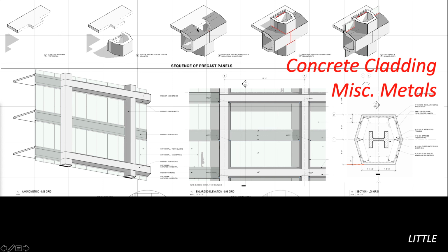Even if you've got a diagrid, you will have some kind of either a self-insulating cover or insulation and a metal cover to basically isolate that from any kind of fire resistance. And I thought this one was interesting too. There's a rain leader. There's basically a channel for the rain to come down through the column, right? So where are we going to run those plumbing drains once they are on the roof? Where are they moving out to? In this case, they're moving out to the columns.